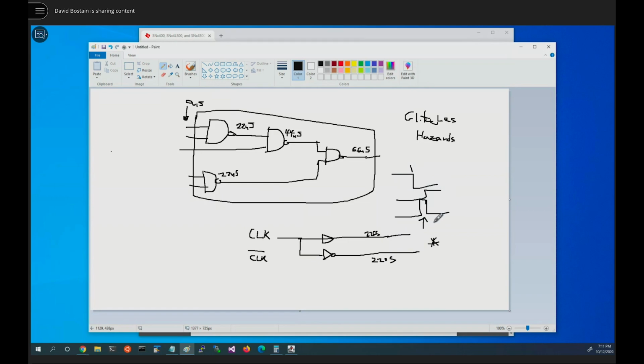So you have to be very, very careful that you understand the timing of your circuit and when things are going to happen. That's what sequential logic brings to the party over combinational logic. While we can arrange things to happen later in time, which is a good thing, we have to be very careful about what happens on the way to getting there. We don't want to look at this signal, at least in the launch a missile way, until we've had a stable signal and really seen what the signal is telling us.